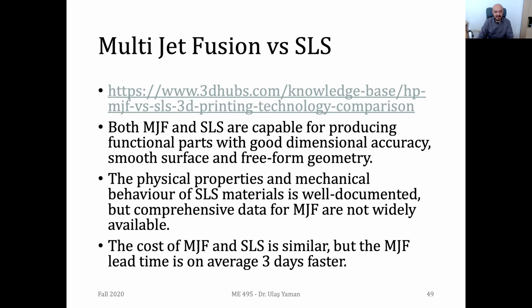Most of the powder is recycled, but on the other hand, in SLS system, since we have laser and heater around, some of the unused powders may be joined together. So that's why in terms of cost, we can say that multi-jet fusion is a bit better and faster.